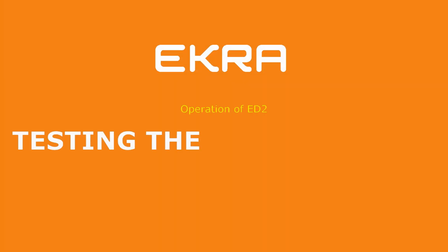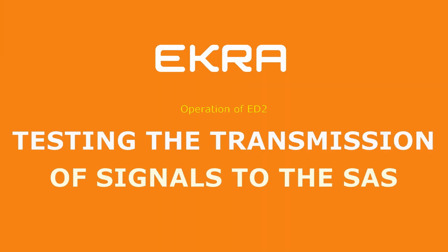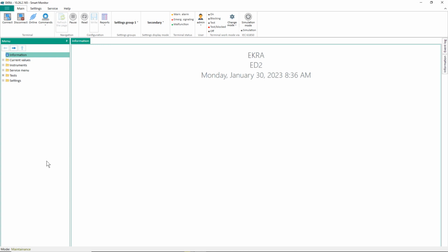In this video tutorial you will learn how to test the correctness of settings of data transfer from IED to Substation Automation System. For testing of signals transmission, switch the IED to the test blocked mode. This is described in the checking of IED modules and functions in testing mode video tutorial.